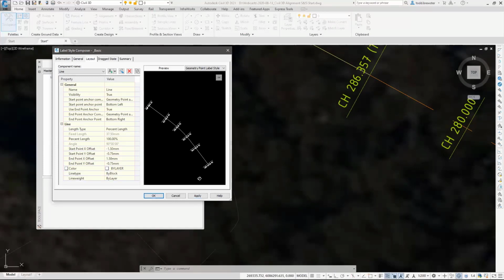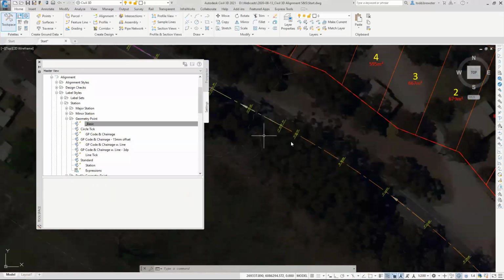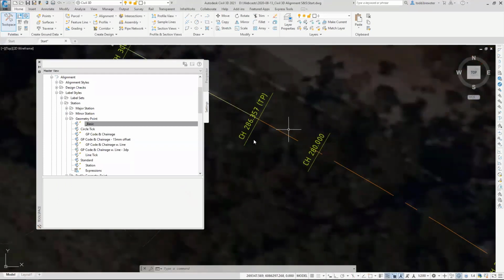Yeah, there we go. All right, now I did mention that you can make these lines a fixed length. So I'm linking these to the bottom of the label, but I could actually link the connection to the feature, and I could actually say that the length is a definitive length in millimeters, which is drawing units. So it'll scale up and down depending on what size you do. So that's the way you could actually change it around. And you could apply that to any of your label types. So push that back. Okay, so now it's gone through and added those labels, and you can see that they're longer when the text gets longer. So that's that linkage I've done to it. You don't have to do it that way. It's just an example of what you can do.